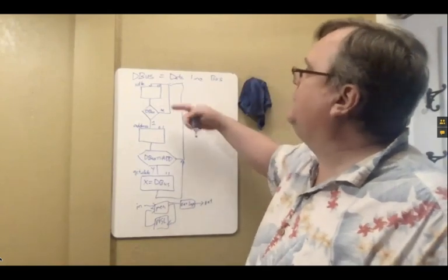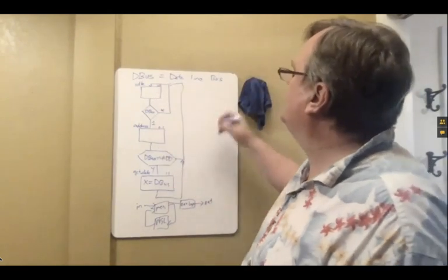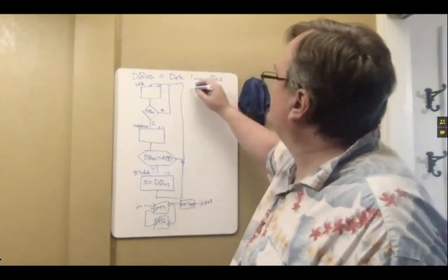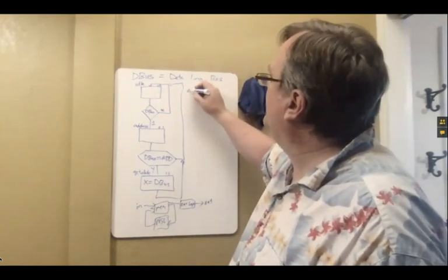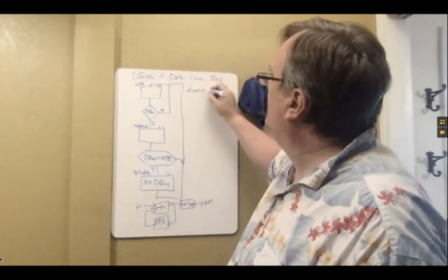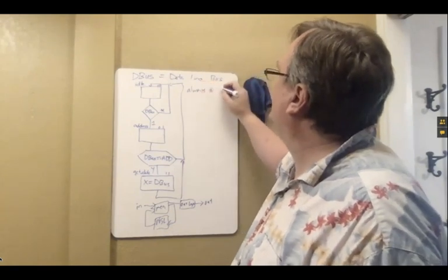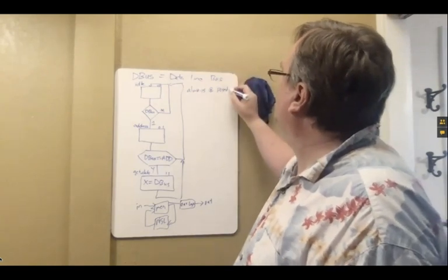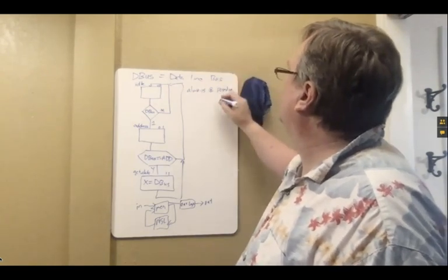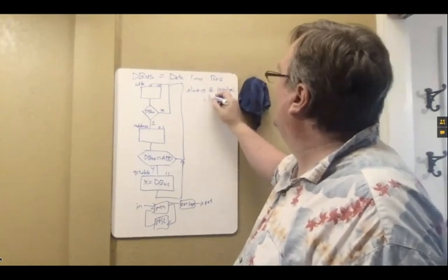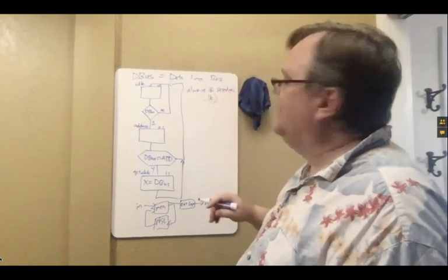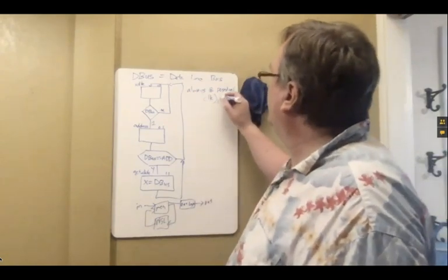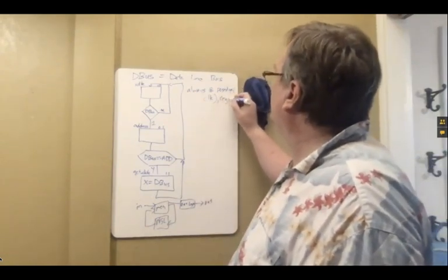And all I need for memory is to hold which of the addresses. So this one is a flip-flop. I need always at, and I didn't put this in, but I should have, the positive edge of the clock. Right now I just have clock. I'm not doing reset. I could, if I wanted, also have negative edge reset.